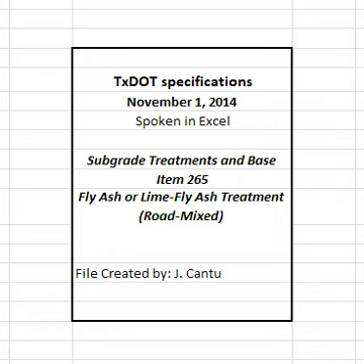Manipulate and thoroughly mix new base with existing material to provide a uniform mixture to the specified depth before the addition of lime or FA. 4.2 Pulverization.